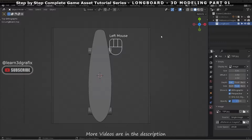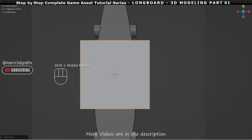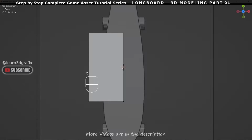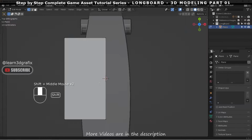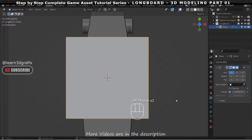We will start modeling the longboard with a simple plane. Press Shift A, go to Mesh and select plane. Hit Tab button to go to edit mode. Press Ctrl R to insert an edge in the middle of the plane. Now select these vertices and delete it. Press Tab button to go to object mode and go to add modifier and select mirror and make sure the clipping is on.